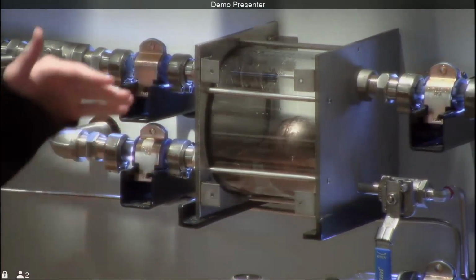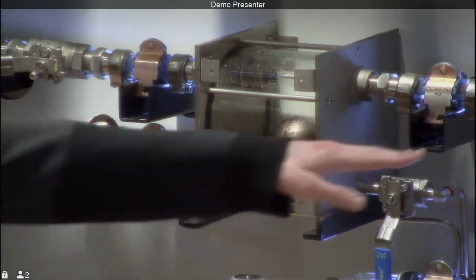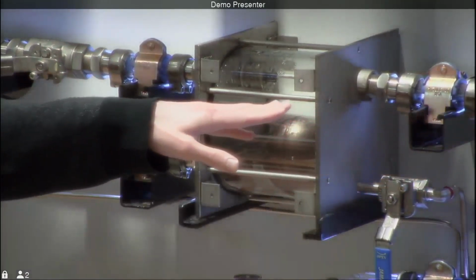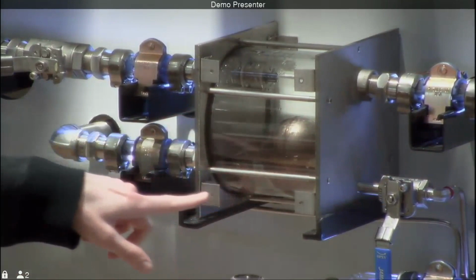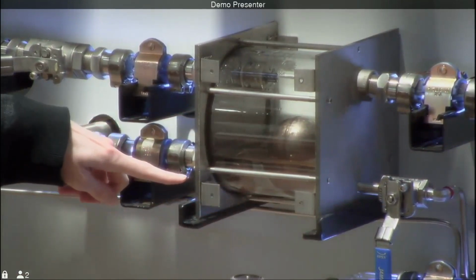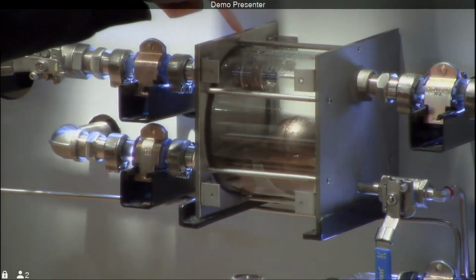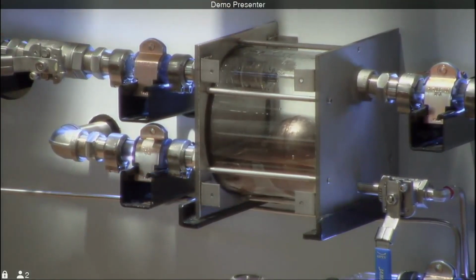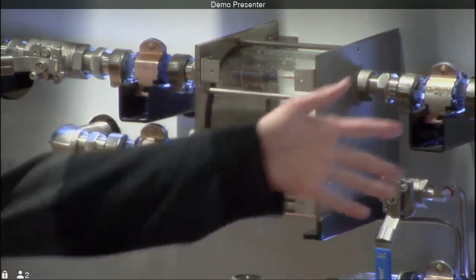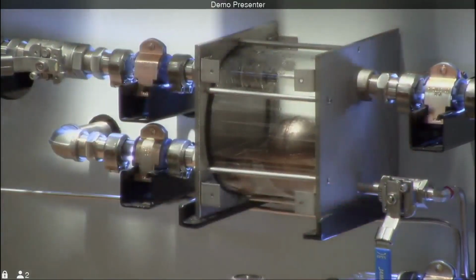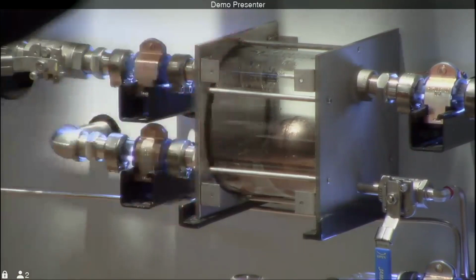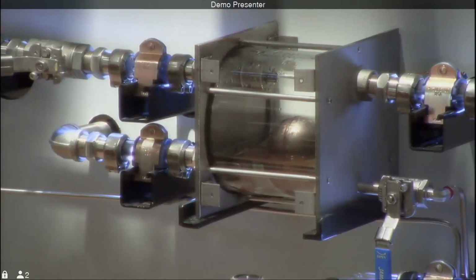Okay, so we have our F&T trap right here. We have condensate coming in from the right, and it's going to be discharging out through our valve and seat at the bottom. We also have our thermostatic element up top here. Some of the main takeaways from this are that F&T traps don't back up condensate into the equipment that you're draining. So they're not going to flood any heat exchanger coils or anything like that.